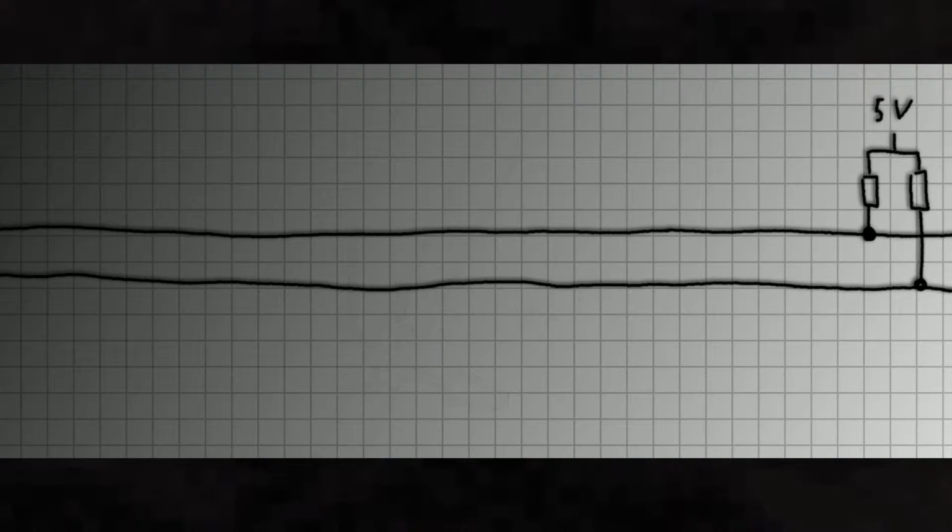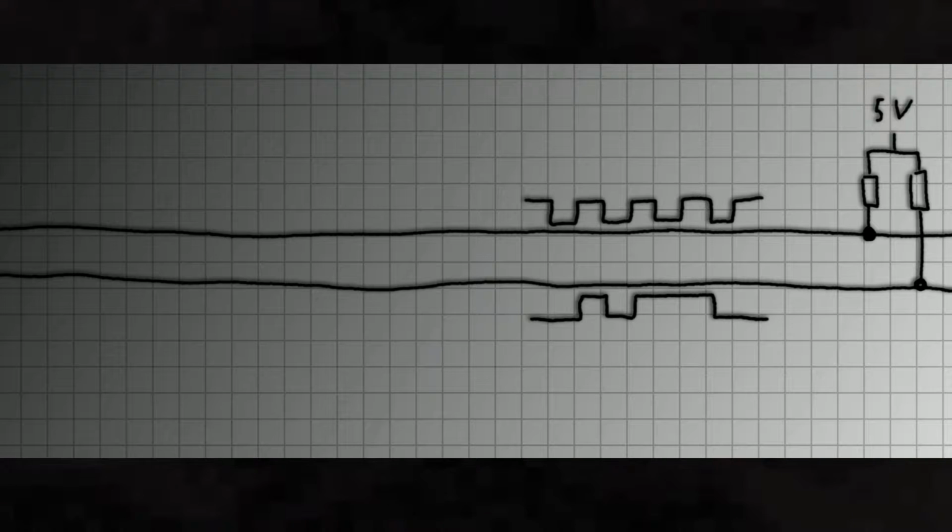One thing to keep in mind is that both wires are always connected to 5 volts, which represents logic high. If any node on the bus wants to signal logic low, all it's got to do is connect the wire to ground. Each line has a particular job. The clock line isn't very spectacular. It carries the clock signal, which is basically a rectangular wave ticking along at some frequency. The data line carries information which is sent by some node and received by another. The clock helps the nodes to stay in sync.